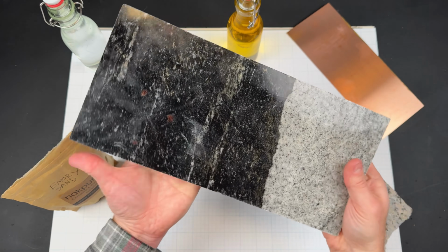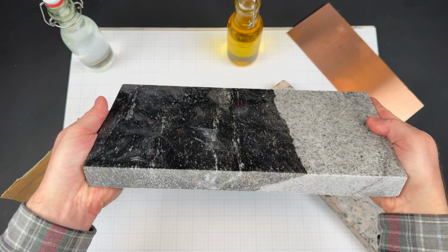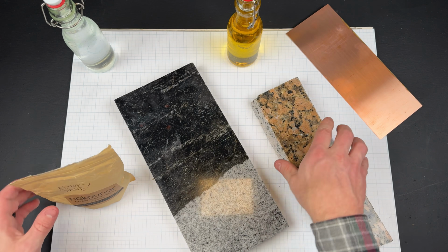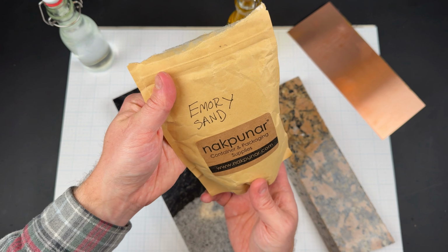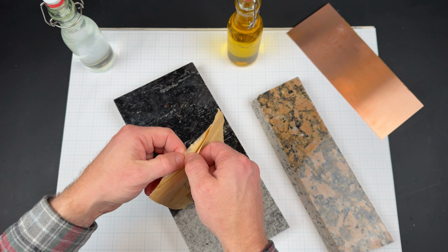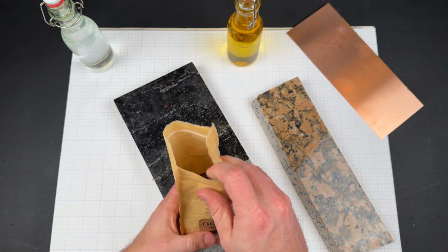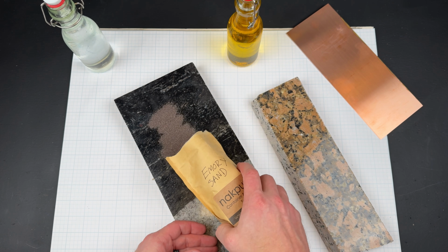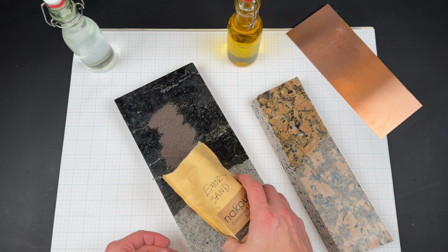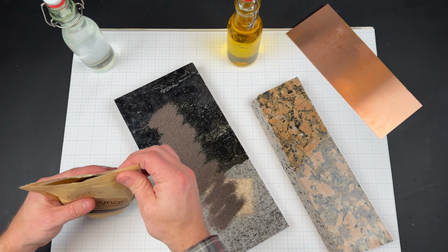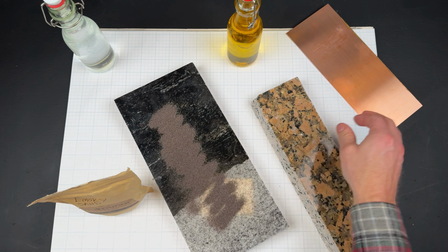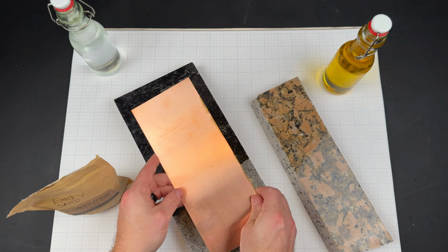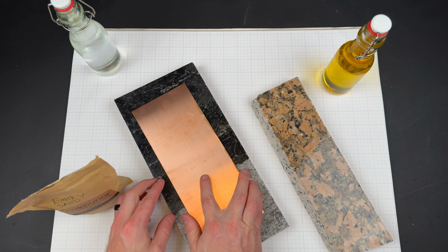This brings us to what type of plate would need to be used to work such hard stone. Now, the plate could have been made from copper or bronze, and then quartz sand, emery, or corundum grains could have been placed between the plate as a lapping medium. These 3 abrasives are all found in abundance in Egypt in wadi deposits, and they can cut diorite or hard granite. If copper or bronze was used, the grains would embed themselves into the surface and create a tough, flat plate that could grind away the hardest stones in Egypt.